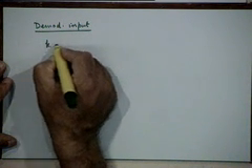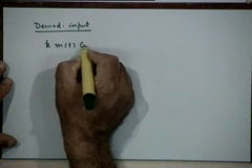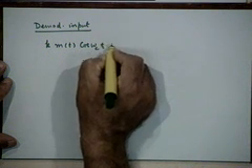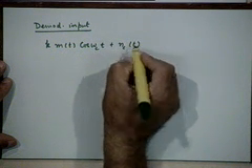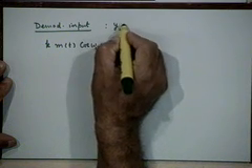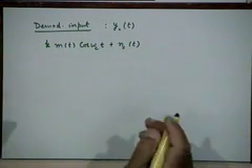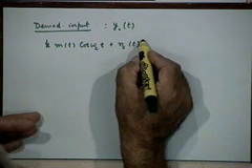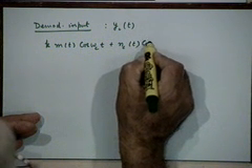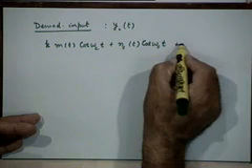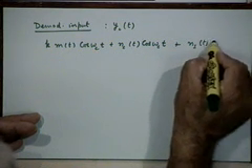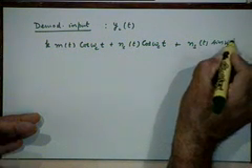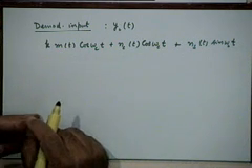It will be k m(t) cosine omega_c t plus n(t). I am talking about y_i(t). y_i(t) is a notation for the signal which is present at the input to the demodulator, right? It will have the modulating signal plus the noise, as the input to the demodulator.